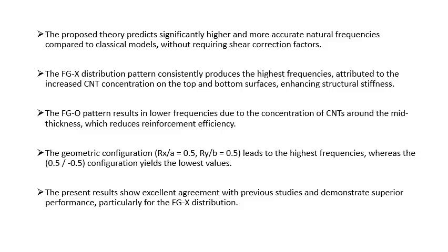The FGL pattern results in lower frequencies due to the concentration of CNTs around the mid thickness, which reduces reinforcement efficiency.